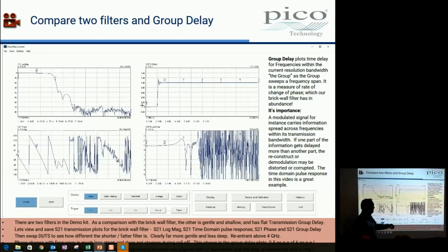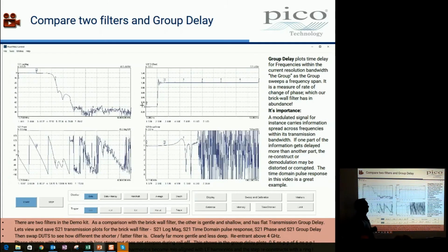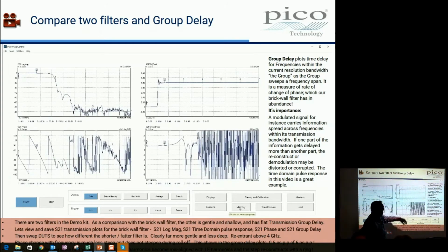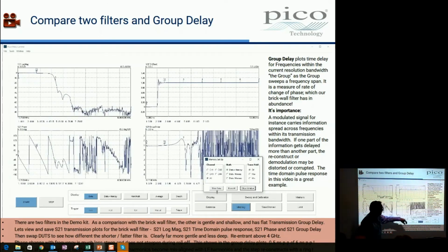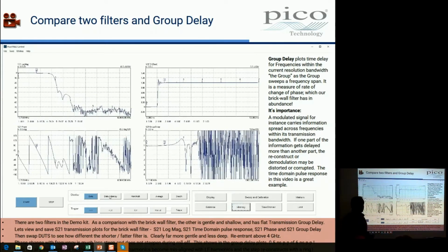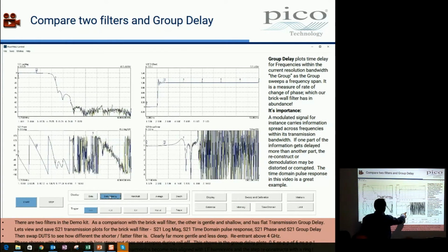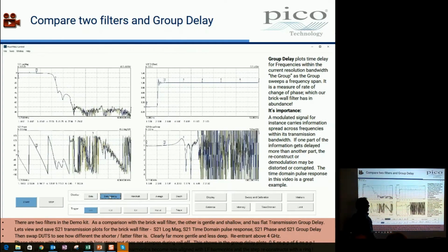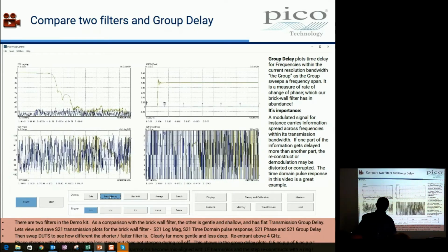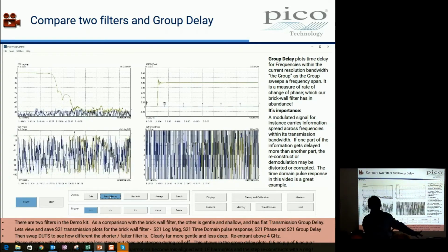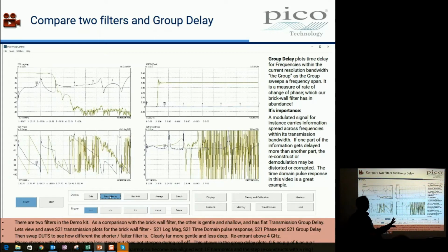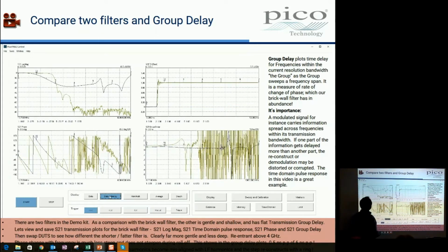In this particular filter, this is not the same filter as we were using in our unknown DUT. We can see 2 nanoseconds peak there, but we can see we're getting 5 nanoseconds or so, minus 5 nanoseconds or so. In other words, this information is getting ahead of this information, and it actually does. This is real. It moves forward relative to the other. It's not a time machine.